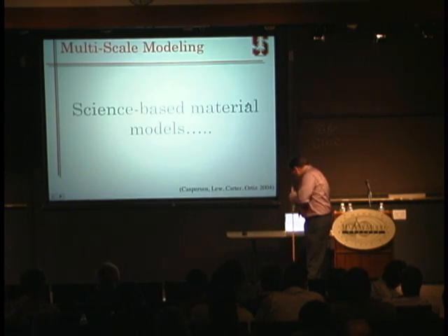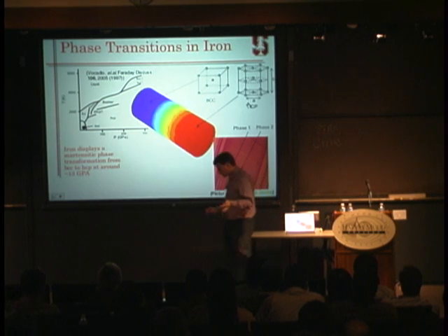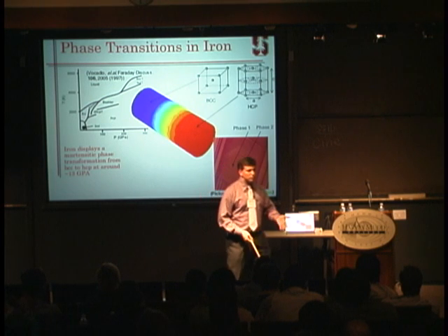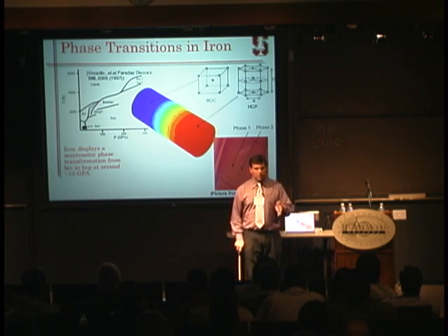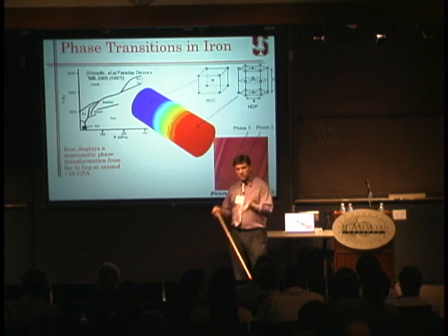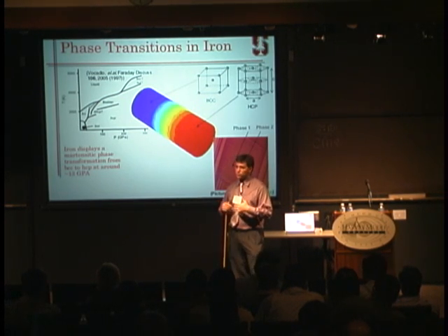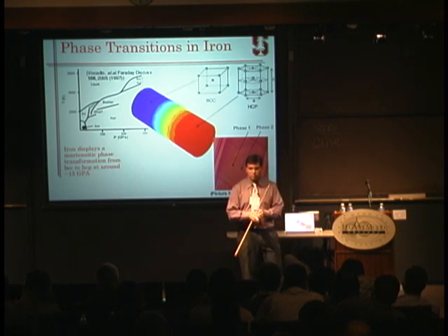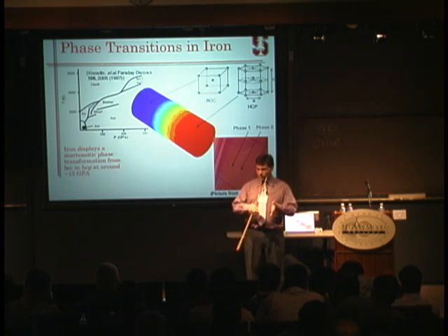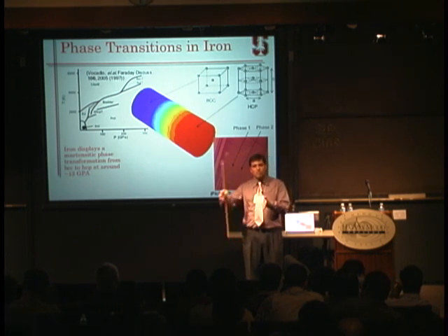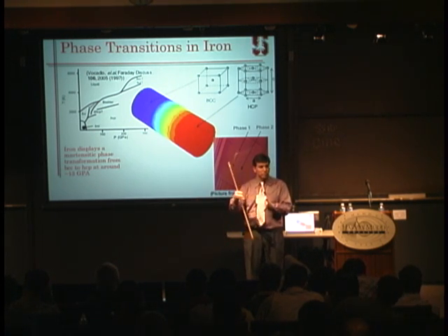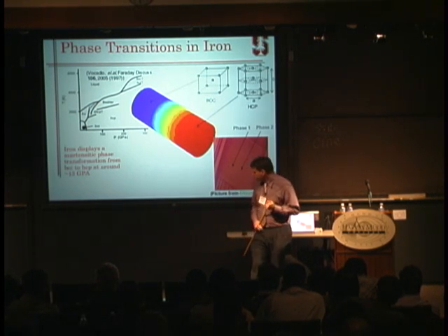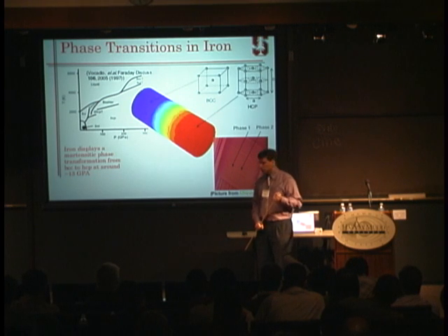So let me now talk about this later point, which is how do we get constitutive relations? How do we compute with the computer the stress-strain relation? The most often or traditionally used method has been to take a phenomenological approach. You take your sample, you go to the lab, you measure whatever you can measure. Remember that we have to measure in a very long range of deformations, and this deformation path could be very different depending on your material. And you use that in your finite element simulation.